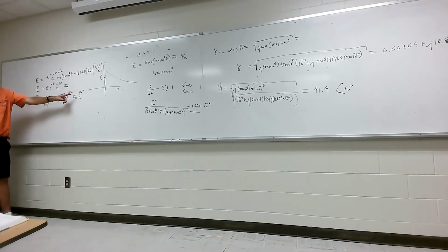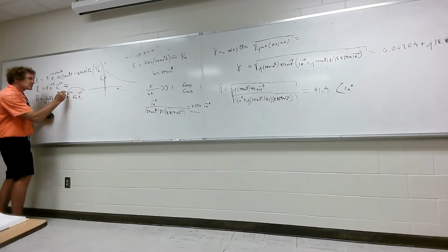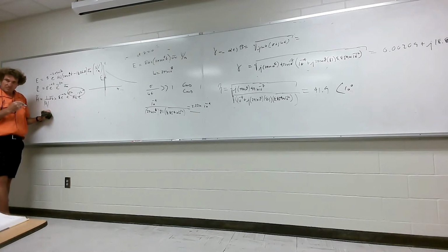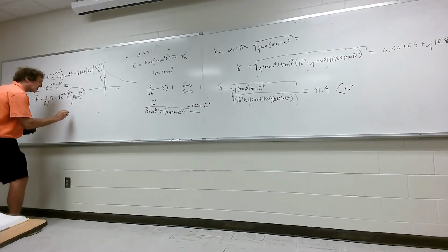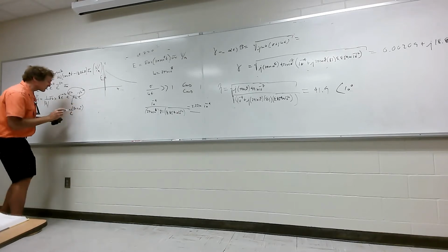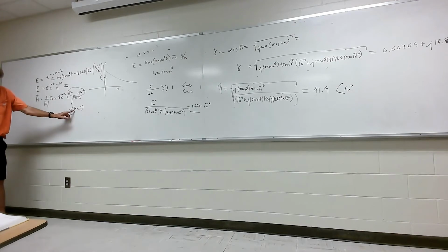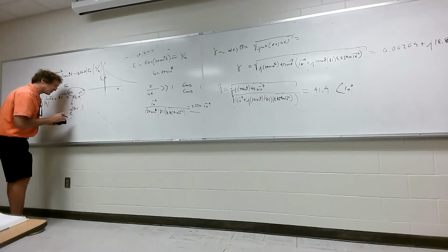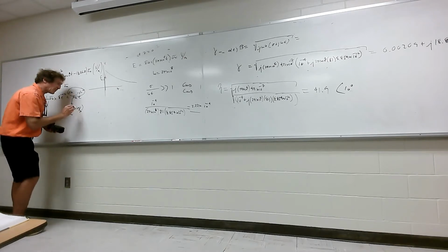Now what happens when I lump this stuff together? Can you see that these two both have the minus j term? So these two would become e to the minus j quantity beta z plus 10 degrees. And it really should be in radians, because beta is in radians per meter times z in meters, so this is radians. Maybe I'll do it this way: pi over 20.